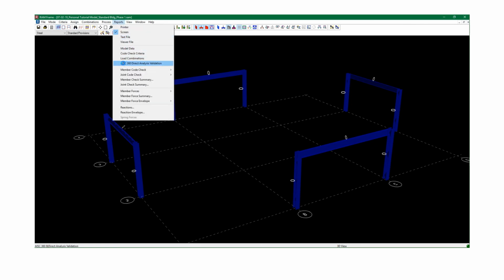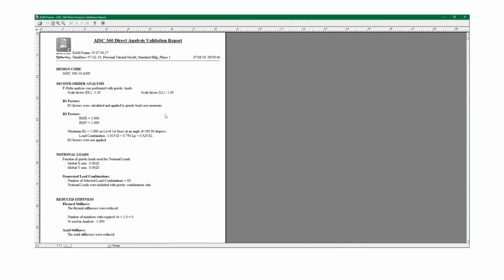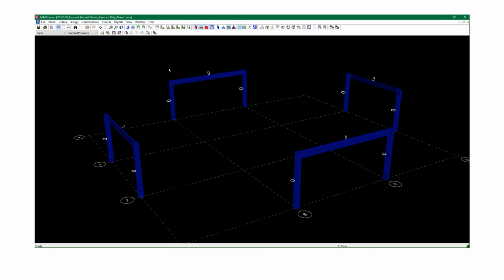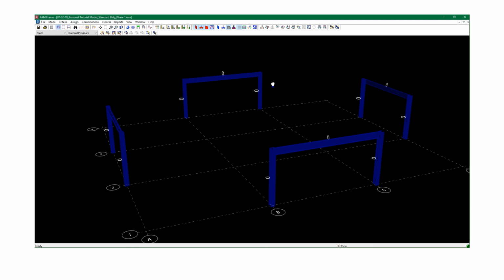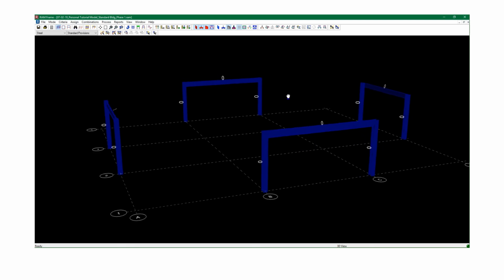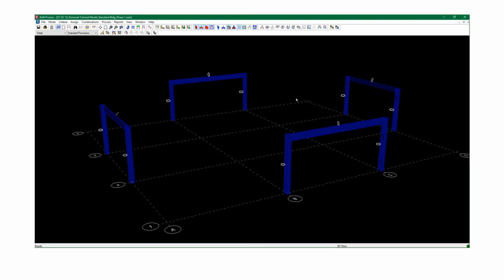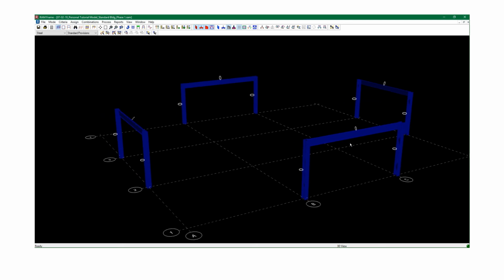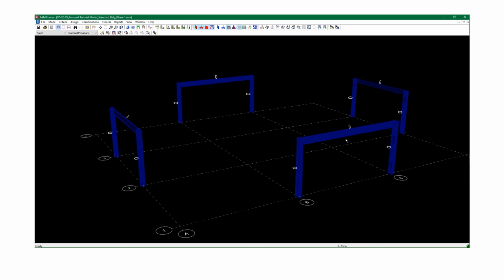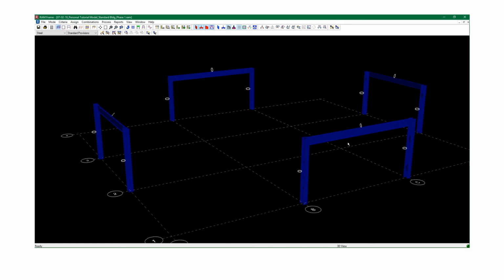Now, let's go back to this report. Even though we're saying that it's good and you are good here, it's still incumbent on the engineer to verify what's going on for that structure in greater detail, and don't use this as a crutch and essentially say that that's all that needs to be done. You may need to investigate what's going on on an individual basis. For example, this frame right here has wind load. How is that wind load entering into the structure?